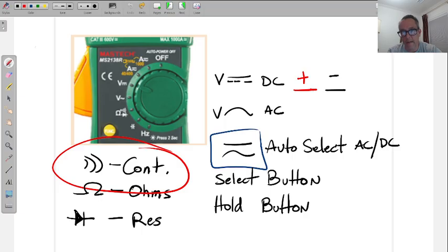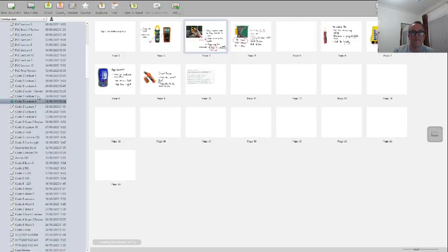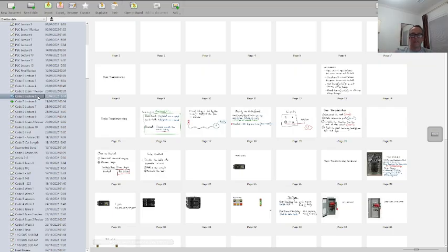That breaker will trip at 19 amps after a little bit of time, not immediately, but after a couple hours. If you have whatever you have running at 19 amps on a 20 amp breaker, that breaker is going to pop. So the difference between sometimes a little bit of amperage, or knowing that there's a little bit of a difference, could be where you want to use the different settings.